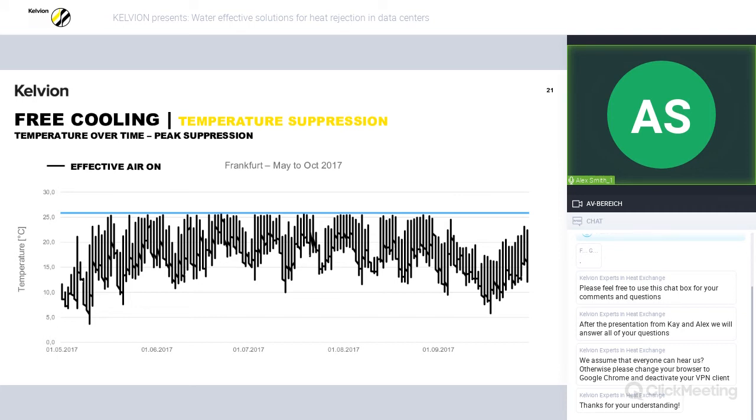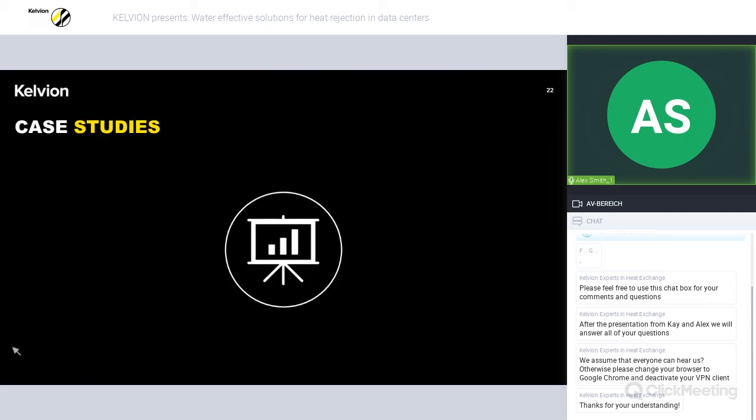Free cooling can occur with return temperatures as low as 27 degrees in this particular case, whereas previously the free cooling would only occur at a peak when it was with fluid temperatures around 37 degrees. In some cases, using water may be one of the only solutions to enable total free cooling. In most cases, it's one of the most accessible means of reducing mechanical cooling hours. The following case studies were done on a 1 megawatt load with a fluid in at 37 degrees Celsius and return at 26. Annual energy and water calculations have been done maintaining an 11K delta T across the load.